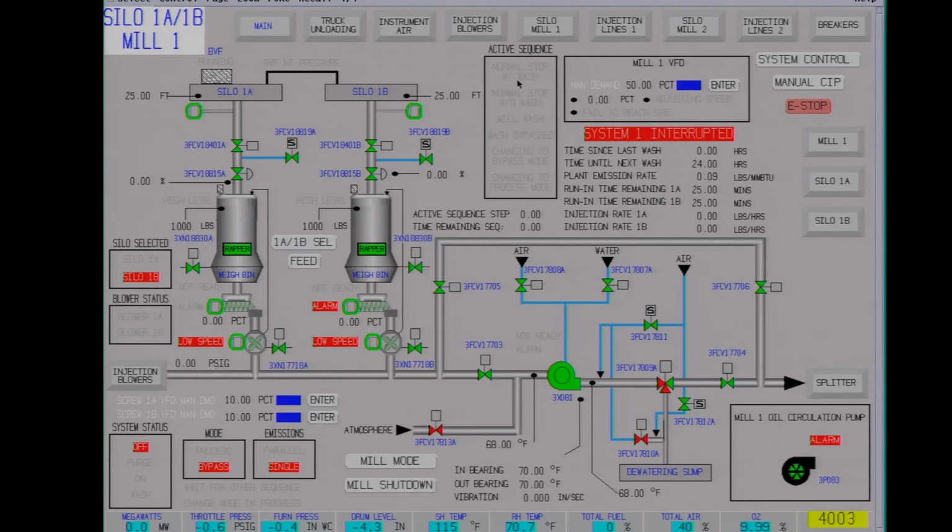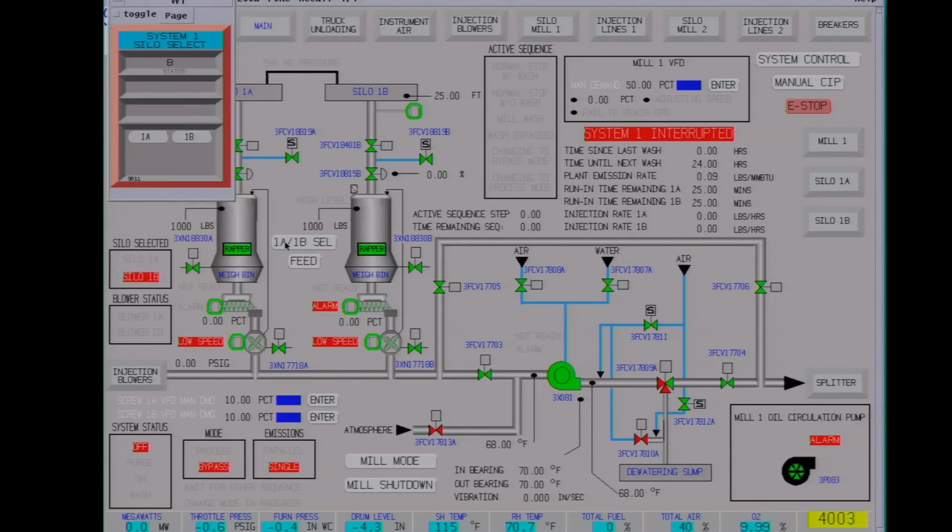We'll start with mill 1. I think we'll use 1A. This here is called the Viper mill. The product goes through here and it's spinning bars that crush it very fine. So it increases the surface area and increases the efficiency of the DSI.